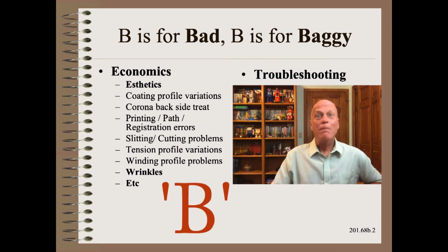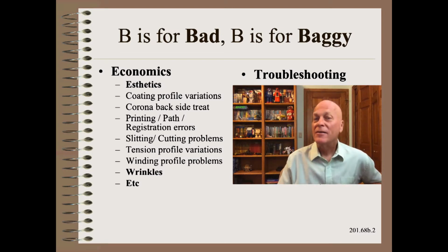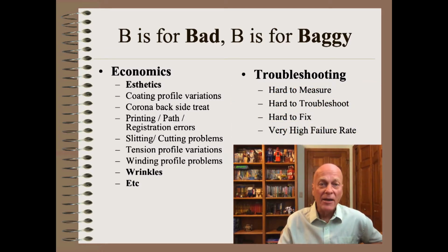B is for bad. B is for baggy. No doubt, bagginess is quite troubling for customers and suppliers alike. It causes a wide variety of aesthetic, runnability, and wrinkling issues. No less troubling is the difficulties for troubleshooters. This defect is hard to measure, hard to fix, and the failure rate is quite high.